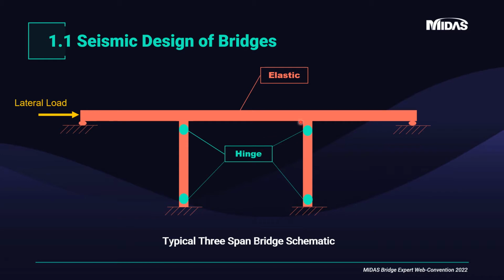and there will be cracking of concrete, which changes the cross-section properties at these locations. Basically, the formation of the hinges allows plastic deformation, which in turn reduces the peak elastic seismic design forces needed to be resisted by the bridge.